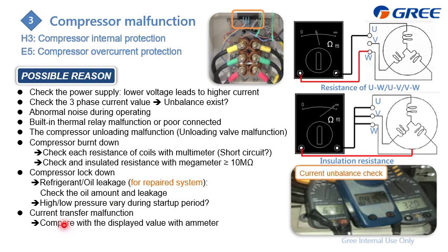And last, we're just afraid that maybe the current transformer is malfunctioning. So on site you can also check the display value on the screen and compare it with the value you measure using this meter, to check whether it is almost the same, to ensure the current transformer is okay.